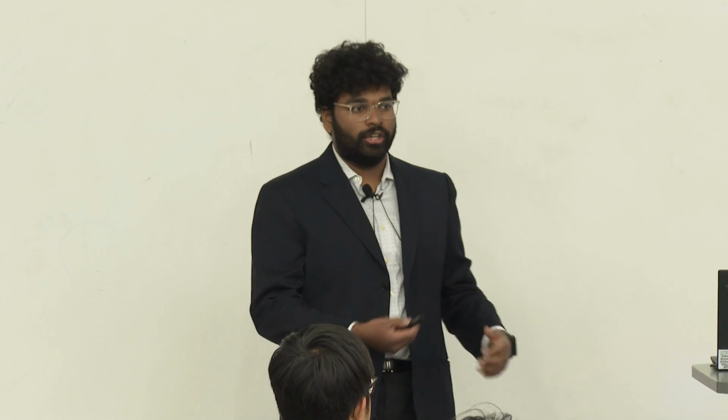So in an ideal world, your yield would be 100%. Right? But obviously you have a certain percent that's random defectivity. Maybe a particle fell on the chip. Maybe an engineer touched the chip. These are things we cannot account for, so we just account for them as random error. But my team basically figures out, are there any systematic defects happening again and again?